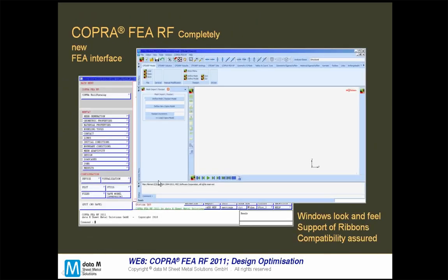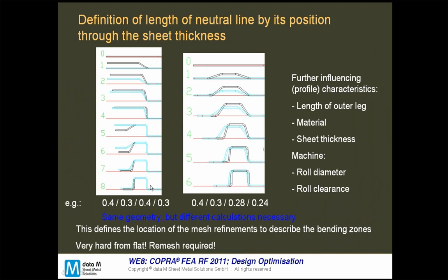So the problem, as we can see here, is that when we mesh the strip, the position of the bends in the flat strip is located on the theoretical position depending on the strip width calculation we have chosen. But we can see here that the strategy itself of the forming will change the position of these bends, because, for example, on the left there is the strategy with two bends with 8 stations.